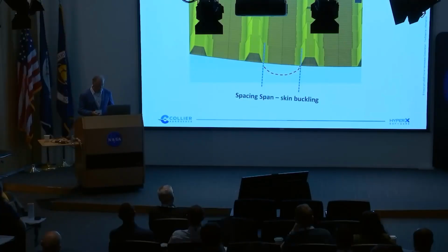So we let it post-buckle at 50% limit load, 100% limit load, and 150% limit load, which is actually ultimate. And we're wanting to know that, but we're also wanting to know that in relation to what's the optimum spacing in that scenario. So I will now go to the software, because I always love doing live demos.